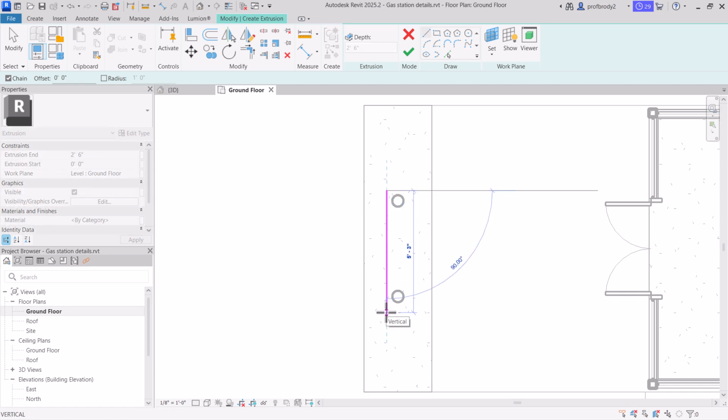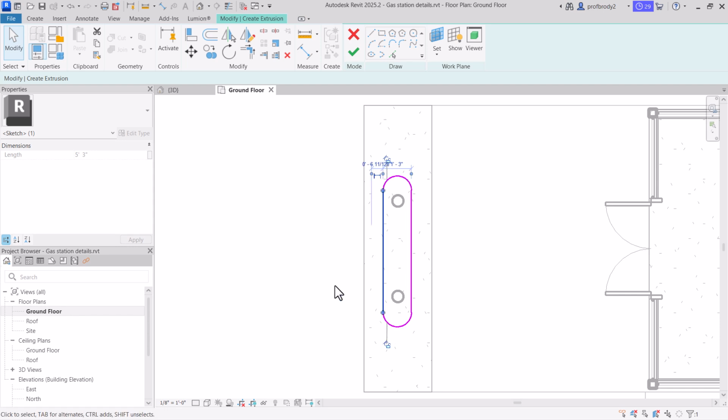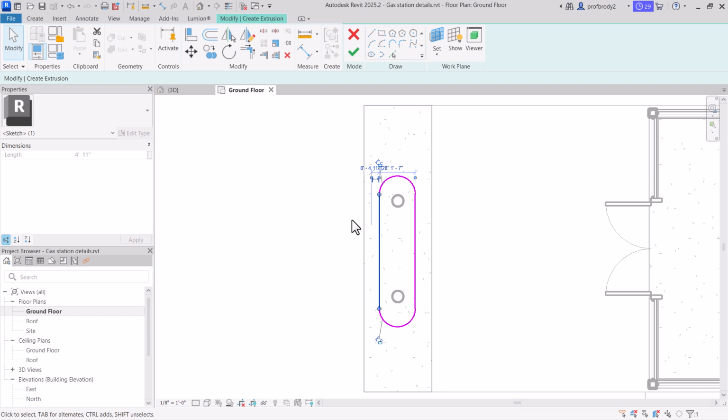Not exactly sure how big it is. That actually looks a little on the small side, but let's draw it symmetrically at first, and then we can expand it. And again, drawing using Revit's drawing tools, super handy and quite easy. There's a lot of tools you can use. Just nudging allows you to change the size of these objects. And we'll take a guess as to the size. Probably a little bit bigger than a foot is what I'd have to guess. And these guys are probably closer in here. Maybe we'll make it 1'7". There we go. Something like that.